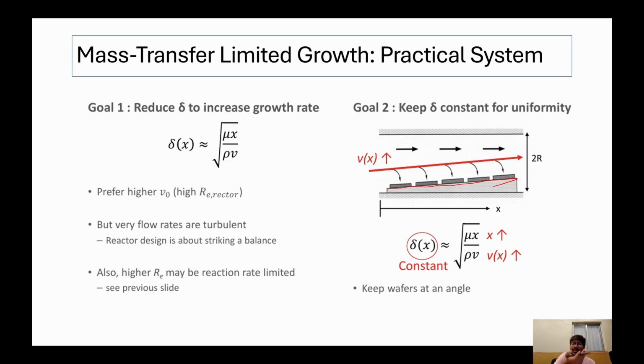The susceptor will have substrates over it. And another thing is, here there is some pressure, high pressure, and you are maintaining the pressure. At this point the diameter is reduced, and because of that there will be a higher, faster flow of the gas. So this stagnant layer will be lesser in this case.